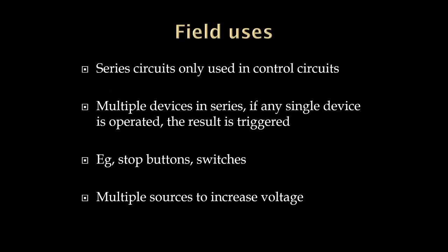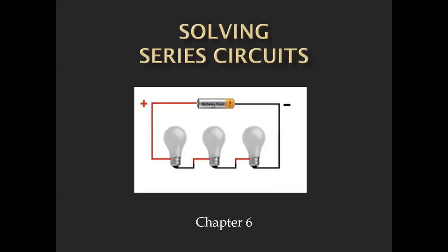So where am I going to use this circuit? Well, I'm not going to power anything with it. We've talked about this a couple of times. If I had a classroom full of light bulbs and I powered them with a series circuit like this, and this one light bulb burns out, with a hole burned in the filament, that gives me an open in this circuit, and it's going to turn the circuit off. So if I blow this middle light bulb, all the light bulbs go out.